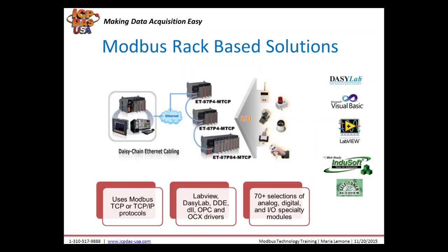In addition to remote I/O, we also provide rack-based solutions in case you need to fit many I/O into a small place. They support up to 128 inputs and are used with cartridge-based I/O. You can daisy chain them together over the Ethernet port. So we have Ethernet-based racks. We also have RS-485 Modbus racks. We have many different types of solutions, over 1,000 products.